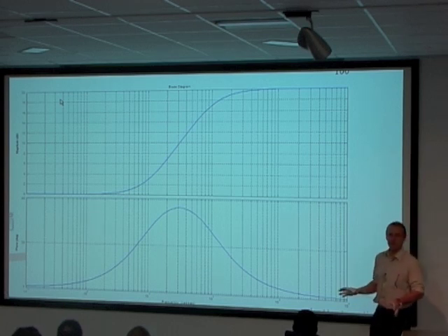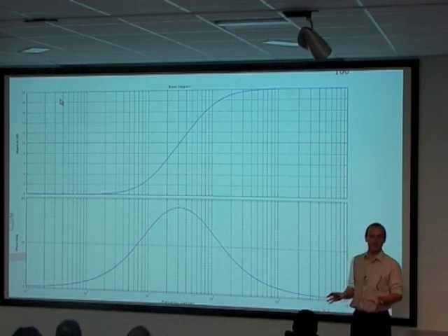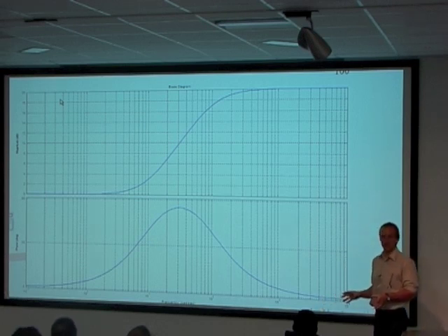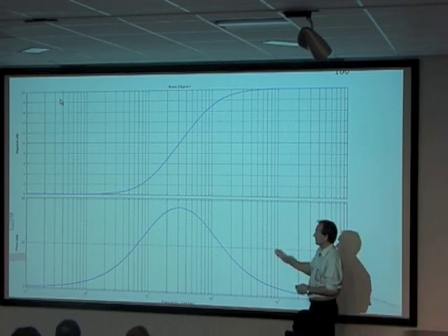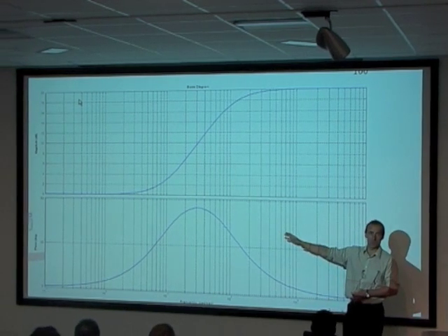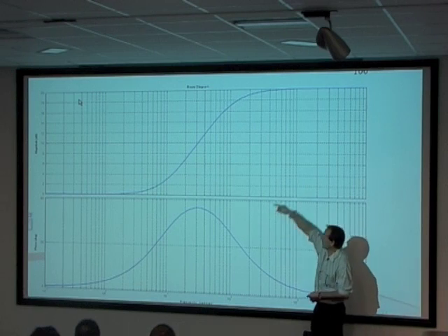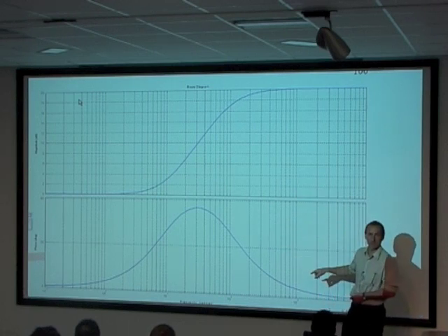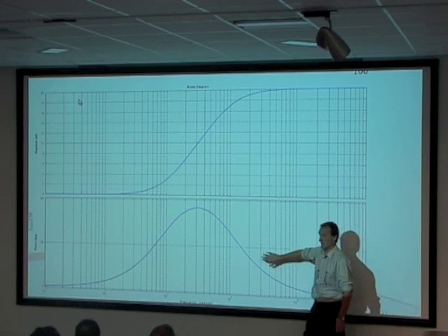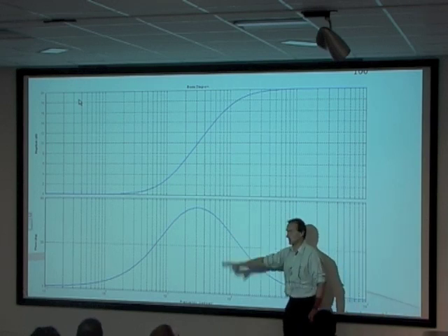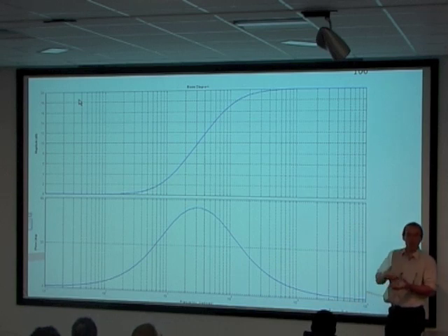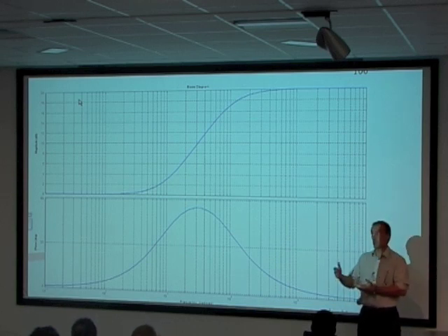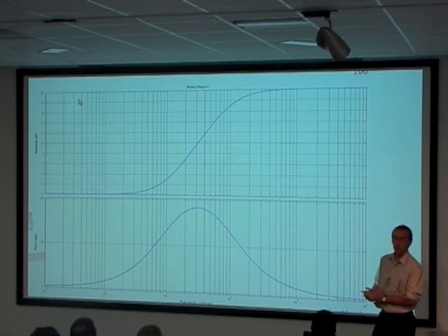There's absolutely no prizes at all for guessing what a lag compensator looks like. All you do with a lag compensator is you make the lag corner happen first. So instead of going up and leveling off, it goes down and then levels off. And the phase bump that you can achieve with a lag compensator is negative. But as a tool to adjust our Bode plots, they're really good.